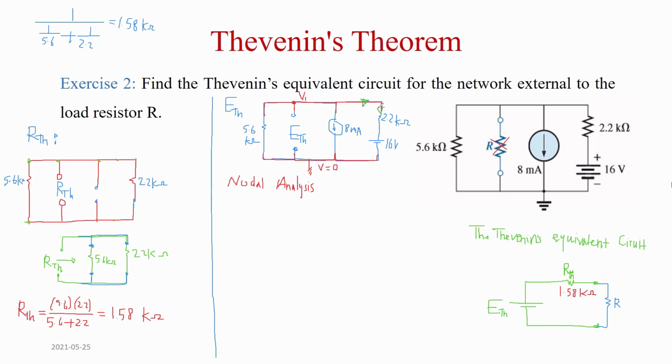Then here, I know the current is leaving. I know the value, so I don't have to guess or assume. This open circuit, current here, I know it's an open circuit, so it's 0. And the current here, I'm going to assume it's leaving because I don't know it. So I have 4 currents, all of them are leaving.